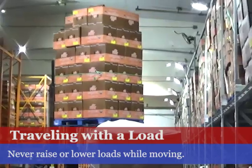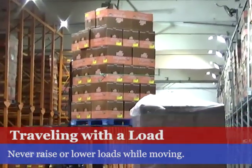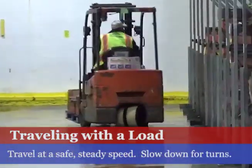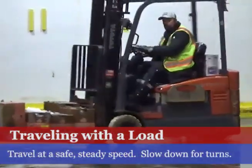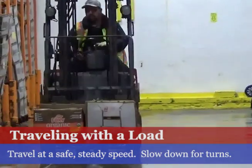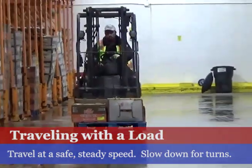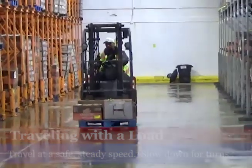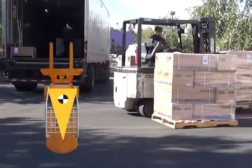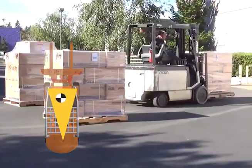Never raise or lower the load while moving. This can cause the center of gravity to shift unexpectedly. Travel at a safe, steady speed, and slow down for turns. Quick acceleration, braking, or turning may cause the forklift to tip over, or the load to fall off the forks. Be aware of the stability triangle, and stay focused on keeping the vehicle's center of gravity in the safe zone.